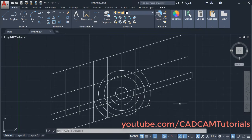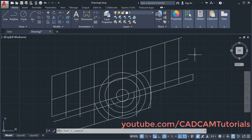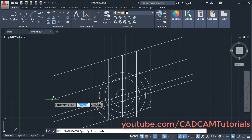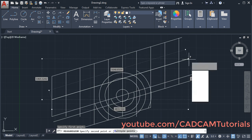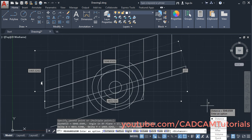Then suppose you want to measure the length of this line, then for that take your cursor to utilities and take your cursor on this arrow and click on distance. Then click the first point and second point of that particular line, click outside. So here it is showing the actual length of that line. Then it is showing length on the y-axis, that is the vertical length of that line, and length on the x-axis, that is the horizontal length of that line. And it is also showing the angle from the x-axis.